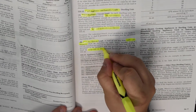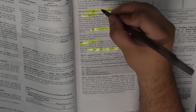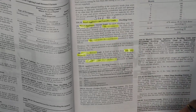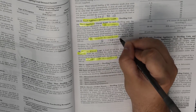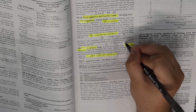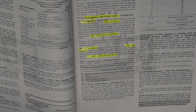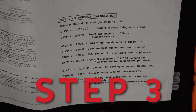Now we're going to label this step number 2, and we're going to say that 2 small appliances are required and 1 laundry is required. So where we can fit it in the small appliance section, we're going to write 2 required, and where we can fit it in for the laundry, we're going to say 1 required. In our test question, it's not going to say, generally speaking, that you have 2 small appliance branch circuits. It's going to say we've got a house or a dwelling unit. Figure out the load. You've got to know that there are 2 small appliance branch circuits required and 1 laundry circuit required. Now we're going to talk about step 3.